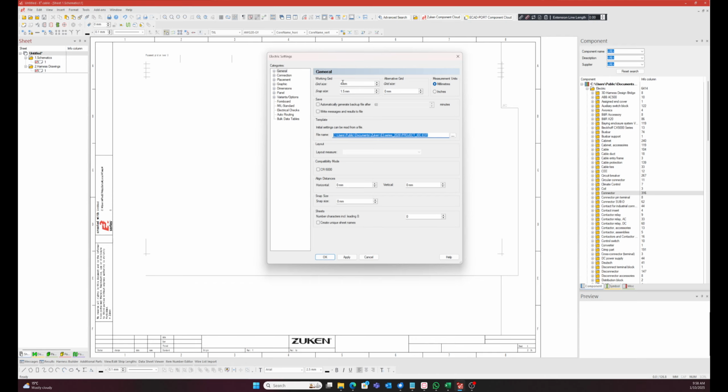So in this case, my grid's correct. It is for 1.5. This is Australian or IEC units, so 4 millimeters. You'd have a factor of an inch if you had it in US. But the alternate grid is one that I recommend you can do. I'll just set it at 1. You can do anything for an alternate grid. I recommend a factor of the grid size.